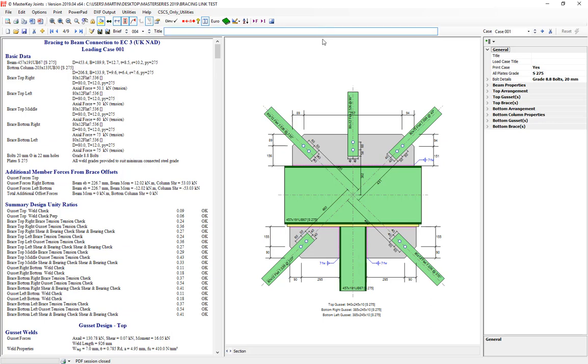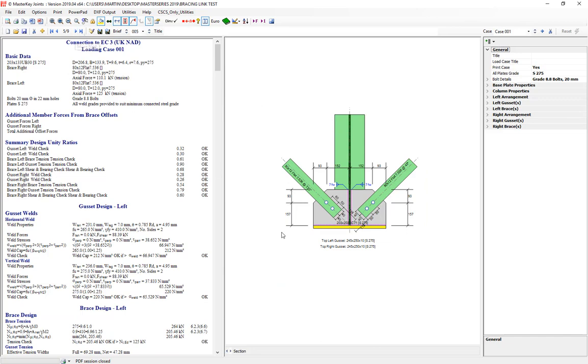So we have a column below but not above, just like in the other connection where we could have a beam to the left and/or right. So there's quite a bit of similarity between the connections. They're just a different orientation and configuration. When you're doing an integrated connection design, you need to select a major beam or major column type of connection to link to the appropriate part of your frame, so it gets this type of configuration right for what you actually have in the physical world.